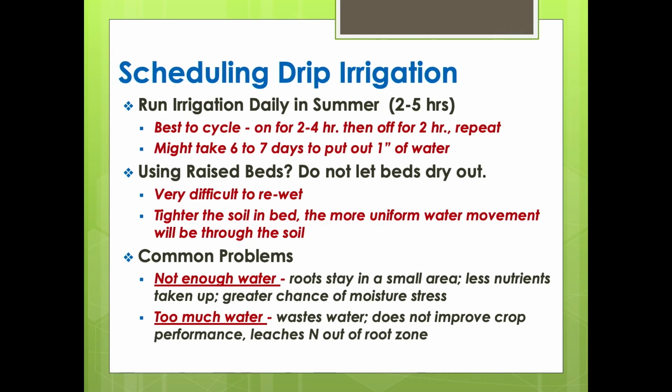But you have to buy a little service kit to make these things work, and you draw a vacuum on it. You fill it up with some dye-colored water, and that maintains it. And you can save these from year to year. You clean off the tip. You always store it in water in the wintertime. You don't let it freeze, so you have to stick it in the house. The tips are usually replaceable, so you can send them back to the company, and they'll put a new tip on it for you, to maintain it.